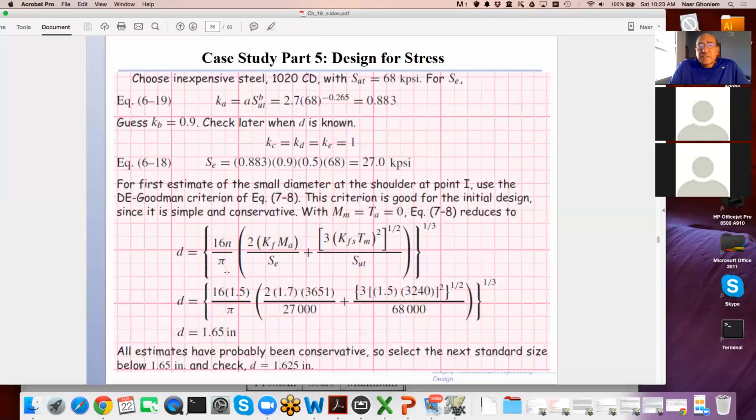The other aspect of the design is the design of the gears themselves, and for the gears there is the Lewis formula that I have in the lecture notes. It is based on simple bending, with some additional factors, and also the wear of the gears must be taken into account. With that we can determine whether the gears themselves are strong enough to take these contact forces, or whether we should modify them.